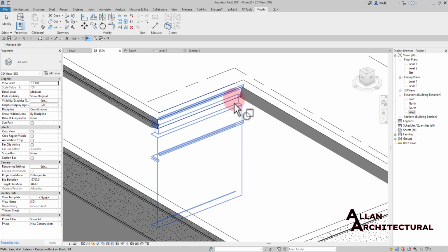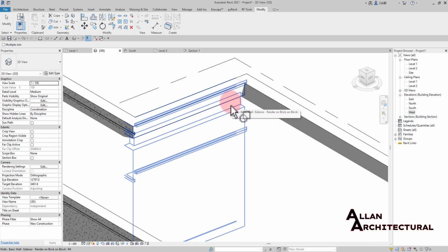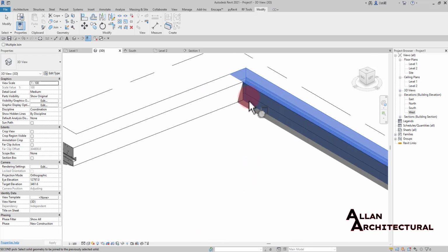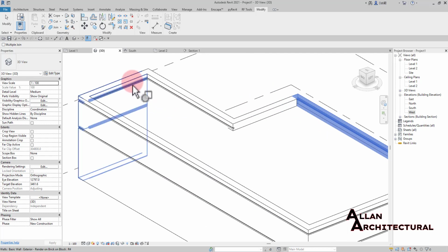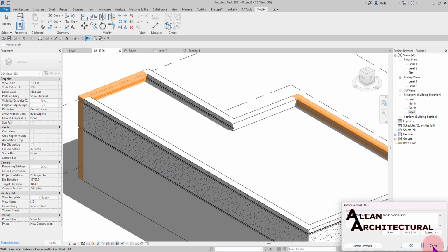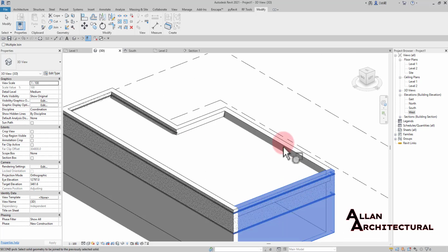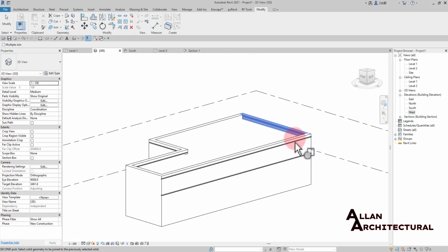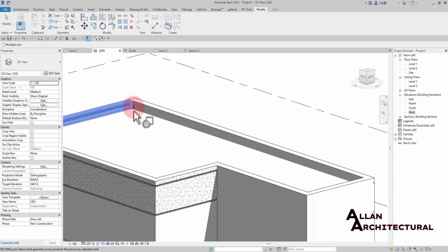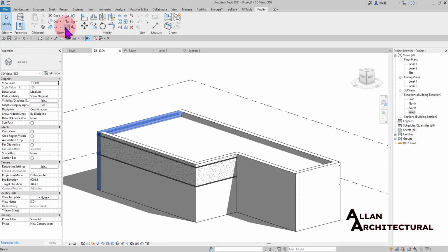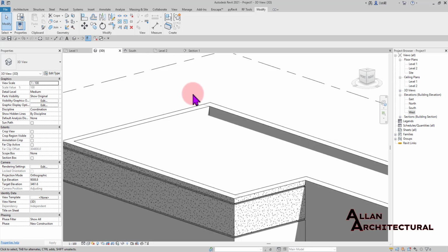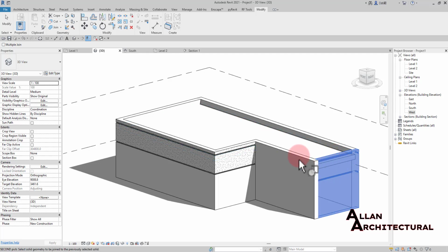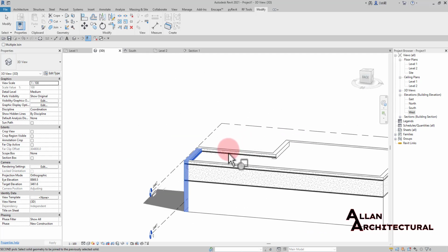Now you're going to notice it creates kind of like a space in there. Our roof tends to go all the way and sit on that structure part. You notice it creates some gap. I'm going to show you guys. Let me cancel out of there, make sure I select all of those, and then select this wall as well. Escape, join, escape out of there, and select your join tool. Make sure you select your roof, and then you join this. Have I joined this as well?